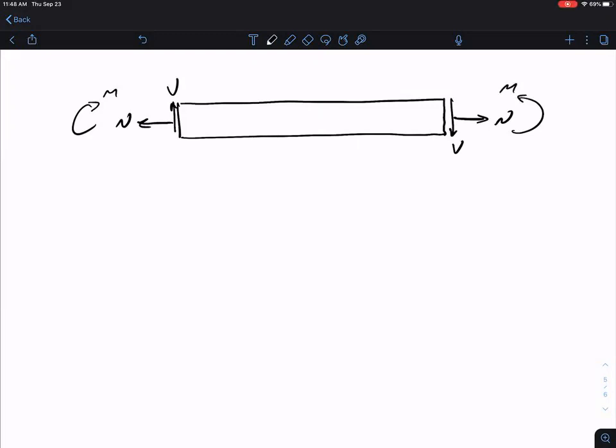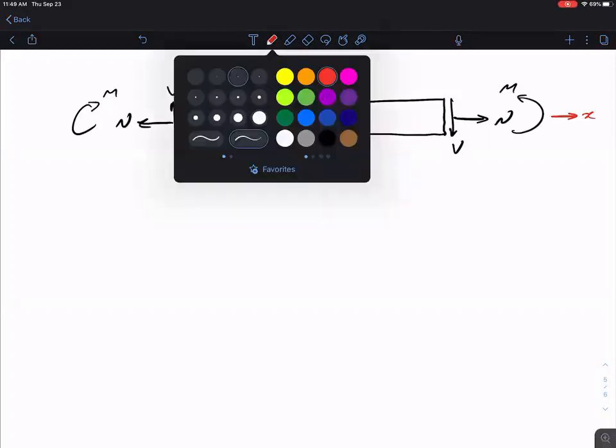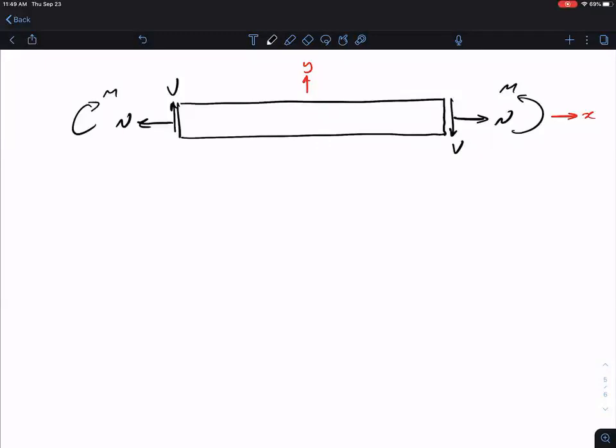And to facilitate coming up with the sign convention for these internal forces, we're also going to specify the local axes of the member. Remember, the local axes are what define the orientation of an element. Now, before we get into the sign convention, one thing we should keep in mind is that these internal loads are really just representations of the resultants of the stress distribution acting over the cross-section of the member. And these can be assumed variations of stress or actual variations of stress.